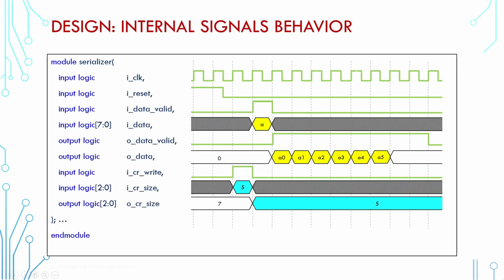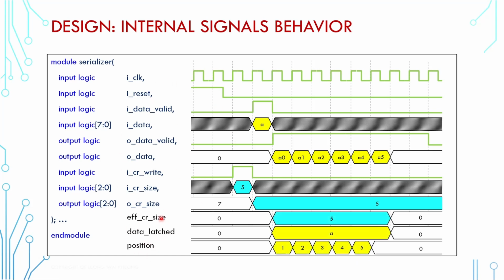And now we can combine all signals and view the behavior. If we include internal signals inside the module, this is generally known as a whitebox view. It gives us a better understanding of a design, but it is generally recommended not to use the internal signals in validation. For one, they are not included in the specification and therefore they can change.